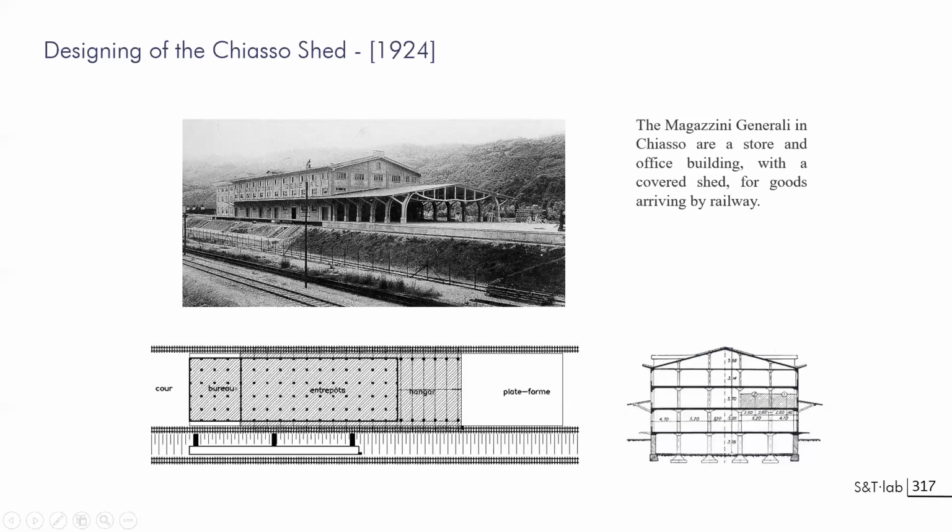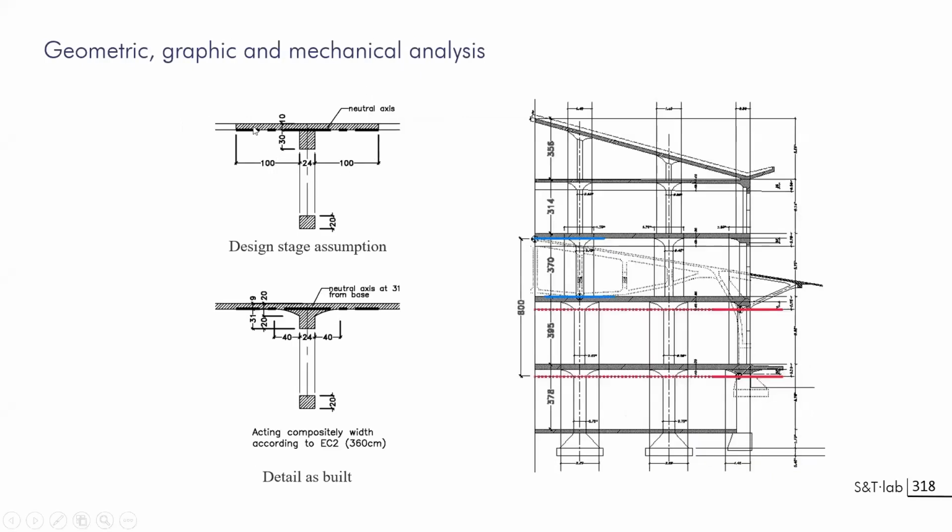And so from this, you can see that Maillart will be implementing two things, two principles, I have to say. The first is about implementing a bending stiffness mechanism with the roof. Actually, the actual roof is this one with a rib and with the hanging funicular line below. And the second is that the geometry has to be aligned on several lines. I will be discussing this.